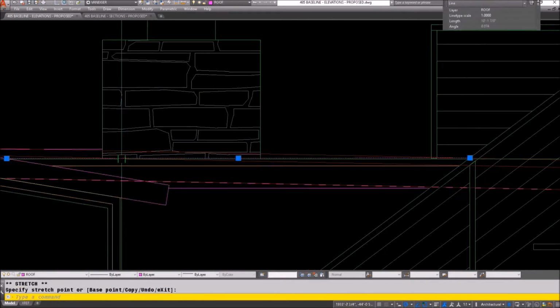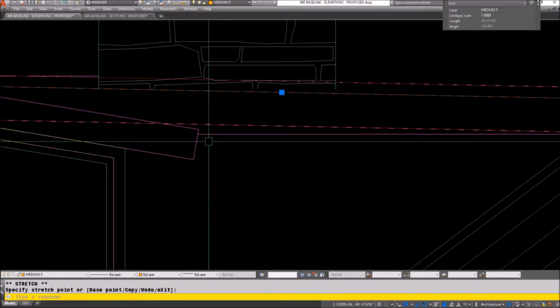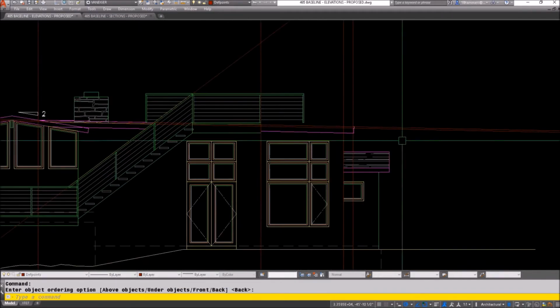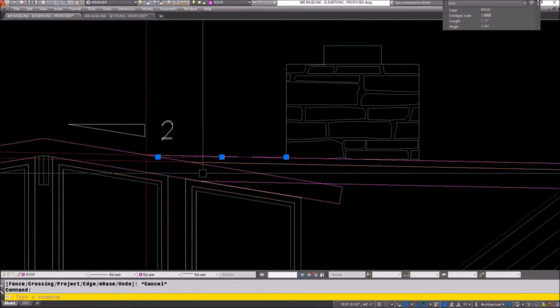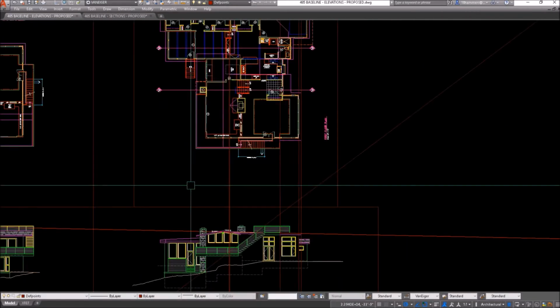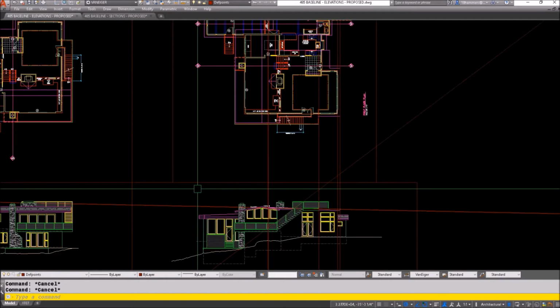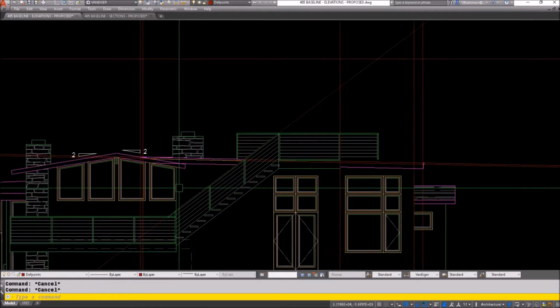And I close it, and it brings it back here, and then I just go down to the lower right-hand corner and right-click that little icon and say update. I have the balloon notifications turned off so that I just know what I'm doing. If I'm working in a drawing like this and I go to the XREF, then I just remember when I close the XREF, I'll be back in this drawing.